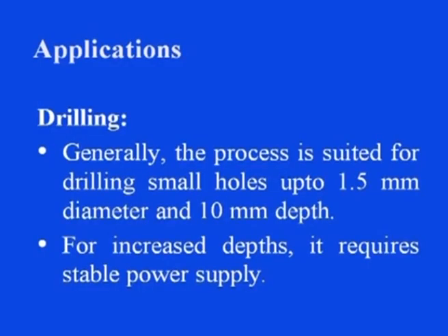Now, let us see the common applications of this particular process. Basically, this process is useful for precision drilling applications. Generally, it is suited for drilling of small holes up to 1.5 millimeter diameter, and depth wise it can go up to 10 millimeter or so.